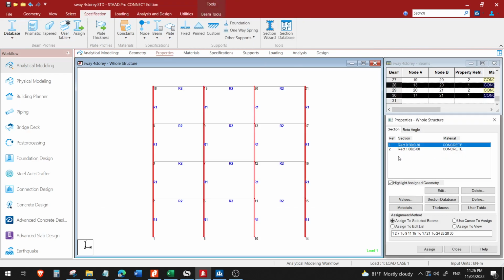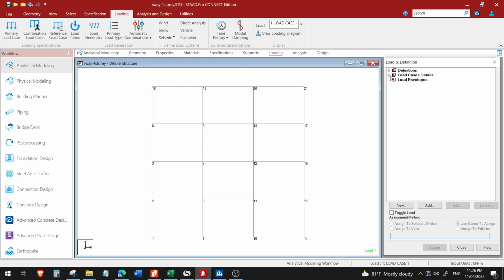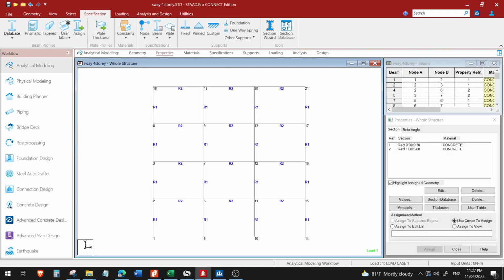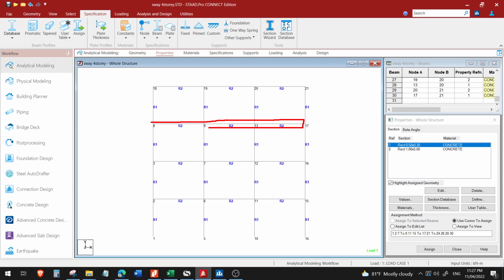properties. I have a hypothetical 300 by 500 concrete column and loaded with lateral force from your earthquake load, right? For example. And then, okay, concrete, but for the girder, I assume a large cross section because remember, in reality, our assumption there is that the girder is actually rigid. Okay, so it is actually rigid and we are avoiding rotation.